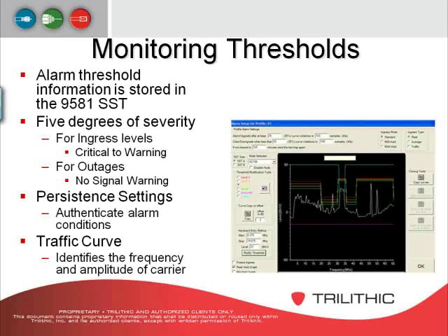That's your traffic curve. So you can bring that traffic curve down into your modem burst, and whenever the modem burst does not cross that line, it will remove that from the screen. So the only thing that's left is just the noise floor. And then at the very bottom, you have a low limit, which you would set just below your noise floor. So if your noise floor dropped below that line, then you would be able to say that node must be offline. So it lets you know that there's an outage going on.